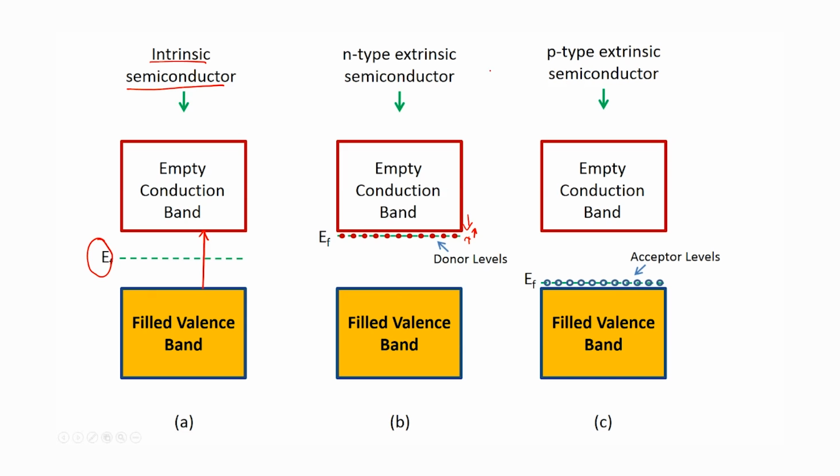Analogous to that, and in a similar but opposite manner, you have the P type semiconductor. Here you are putting in materials as dopants which have one less electron than the base material that is present. So, it creates a bunch of acceptor levels. Here again the electrons which are at the top of the valence band can go into the acceptor level by just doing this small jump, and it enables the material to start functioning in some interesting ways. So, this is the P type extrinsic semiconductor, and that is the N type.